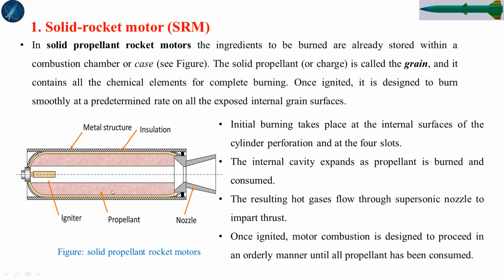Okay, there is the propellant, and the igniter, a solid propellant igniter. We can fix it at some appropriate position. The nozzle design is here, meaning convergent, divergent, and throat condition. So this is a complete assembly of a solid rocket motor. So you are expected to design at least this motor. From this time onward, just consider how to design this motor.